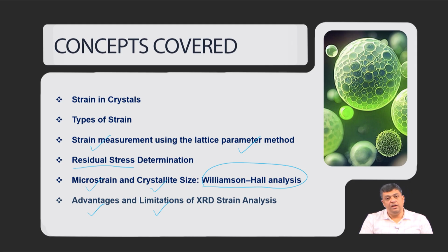For example, if we say that there would be significant change in the lattice parameters if you change temperature, for example, from room temperature to 50 degrees, then there is a lattice strain and overall you start seeing thermal expansion in most of the materials. Please note, I am saying most of the materials because now it is also understood that there are materials which show negative thermal expansion.